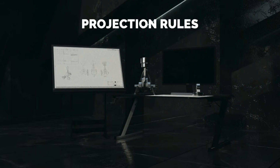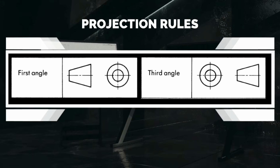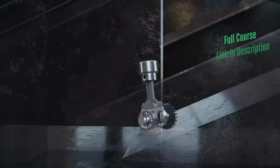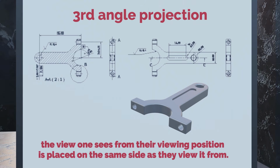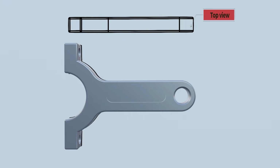There are 2 laws that define how the 6 orthographic views are related to each other: first angle projection and third angle projection. In both cases, the views are the same, but the position of the views with respect to each other differs. In third-angle projection, which is common in the US, the views are arranged such that the view one sees from their viewing position is placed on the same side as they view it from. For example, the plan view, also called top view, is seen from above, so it is placed above the front face because it is viewed from that direction.